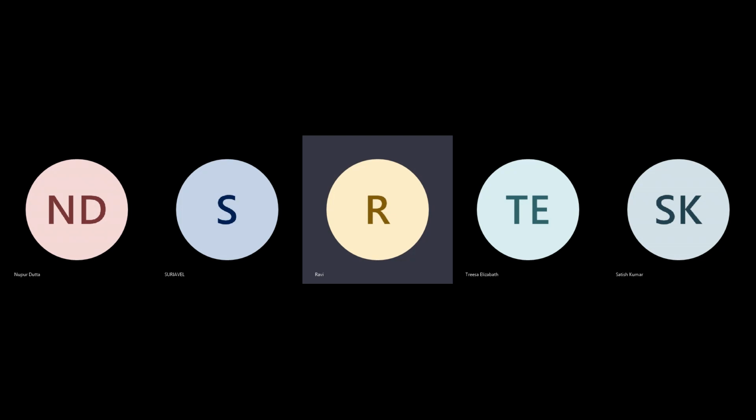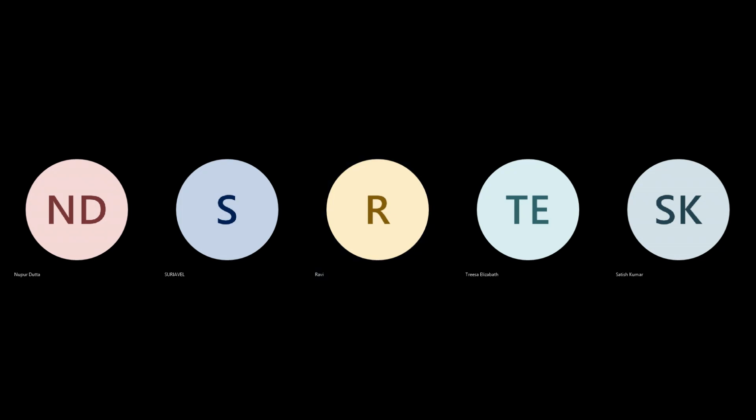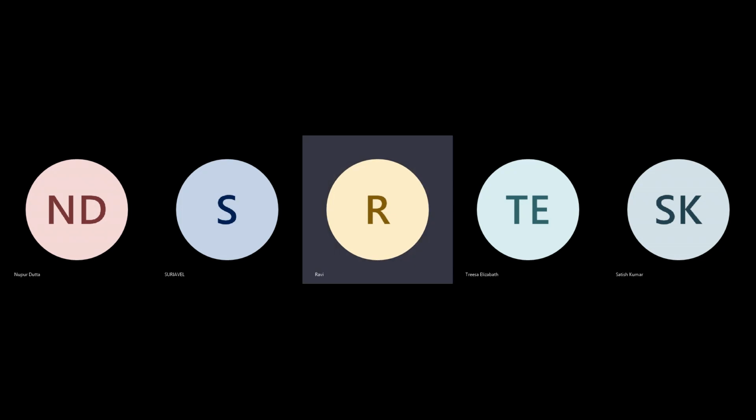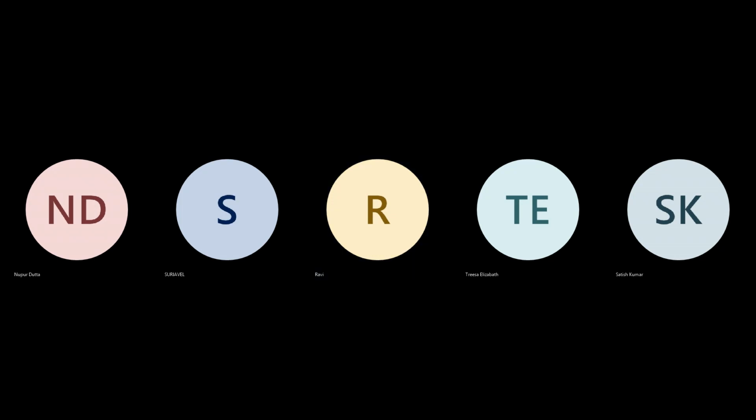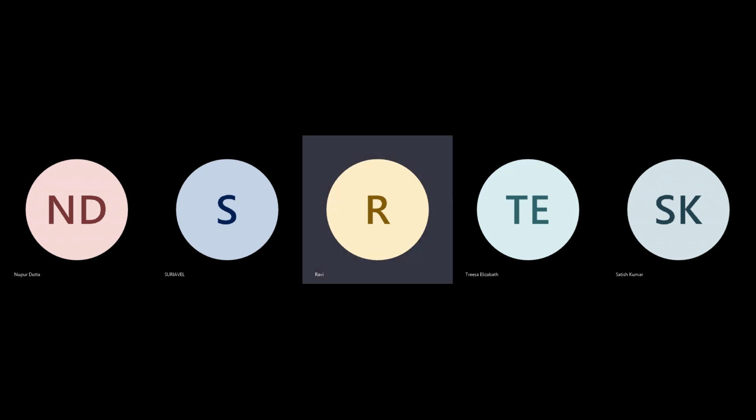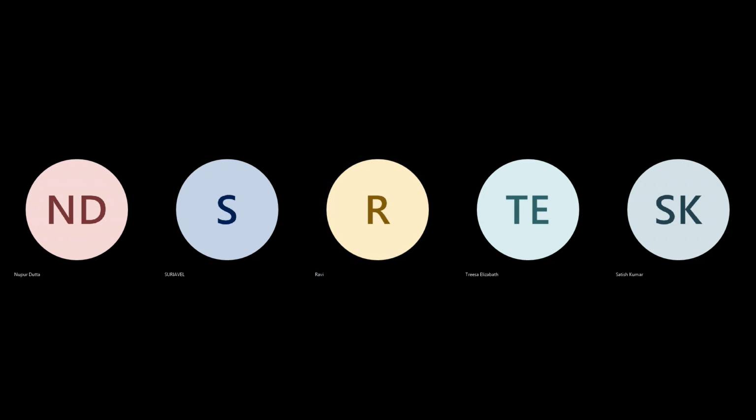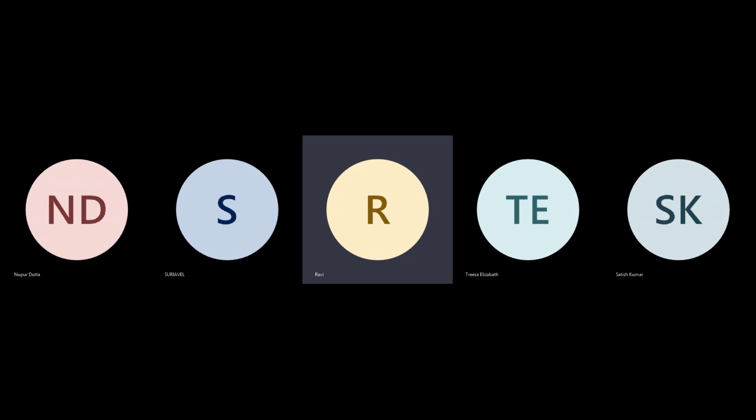After buffering, you should see the DRVs also. After high fan out net synthesis, if they ask what the step is, you will say buffering. No sir, first time buffering is not the first step. First is sizing of the cells.